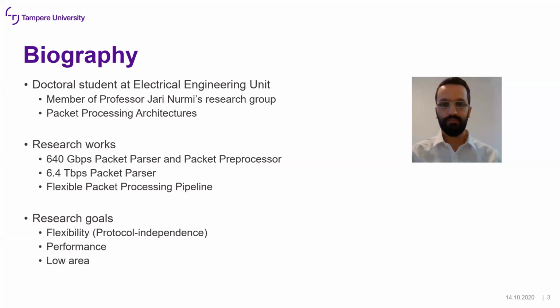And so far in our research works, we have multiple variants of a programmable packet parser and the packet processing pipeline. The research goals are flexibility, which in this context means protocol independence, so that you can have hardware that can provide functionality for different protocols by means of software without any change in hardware, and also at the same time maintaining the required performance level and keeping the area low.